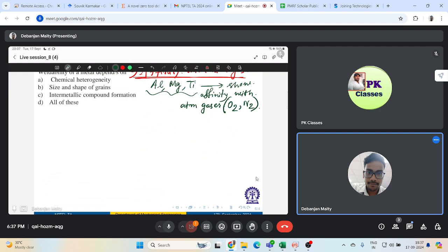Most metals at high temperature during fusion welding, if they are not protected with some flux, or if you're not doing your experiment in vacuum condition, will always react with air elements, and oxide and nitride formation will be there. They will form oxides, nitrides, sulfides, hydrides. Those can all be observed in the form of inclusions in your weld metal, right?